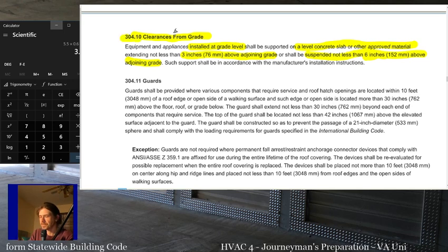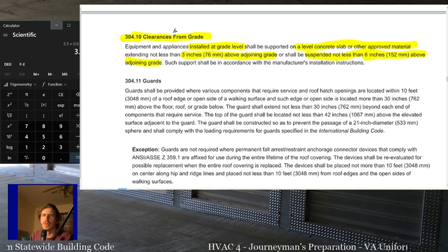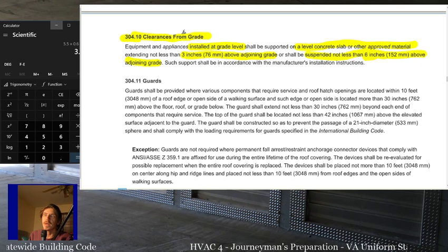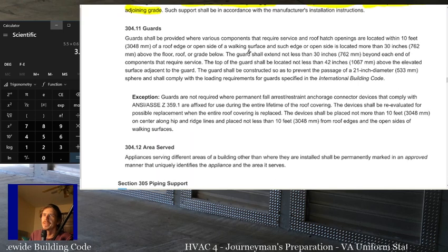You know, another good example would be I went to a supply house one time and I asked for flex duct with R6 insulation. And they said, we only have R8. Really? Yeah, because all flex has to have at least R8 insulation. No, all flex has to at least have R8 insulation in an attic. It doesn't matter what the insulation is if it's just in a plenum ceiling. But again, supply houses and manufacturers sometimes start creating things because people tell them stuff that's not true. You'd be surprised, okay? Not everybody actually understands things. Hopefully, by the time we're done, you'll actually understand them.